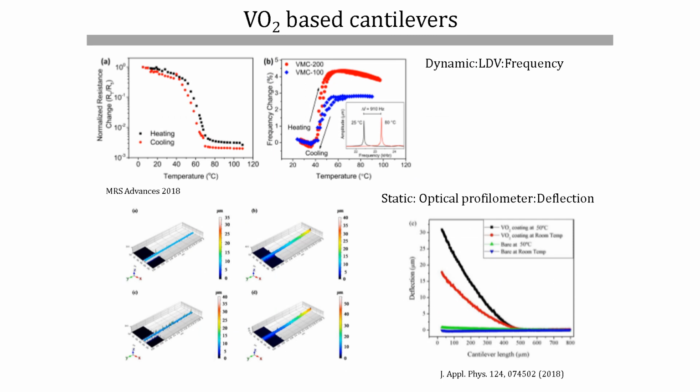This is one of my works with Dr. Lima here. We were able to use a silicon cantilever. We didn't fabricate it as such. We were able to use the silicon cantilever as a photothermal actuator, which means if you shine light on this material, which is a semiconductor metal oxide, at a particular temperature it suddenly shows huge deflection, which can be used for multiple purposes.